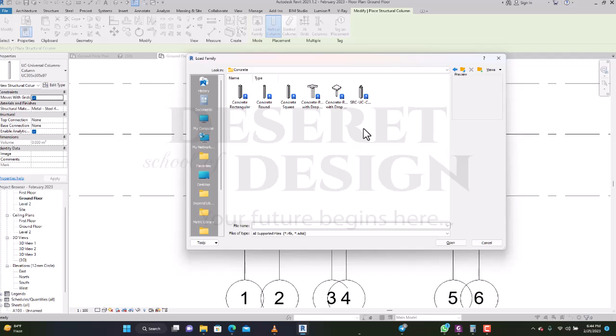You can see the beam protruding. It's like part of the design, especially church design, where you can see all the column sizes and everything. So you need to know what you are doing per the column you want to place. Is it flush? Are you assuming that the moment you do your plastering you don't see the column again? So you should know the width of that column has to be flush with your block wall. Do you get it?